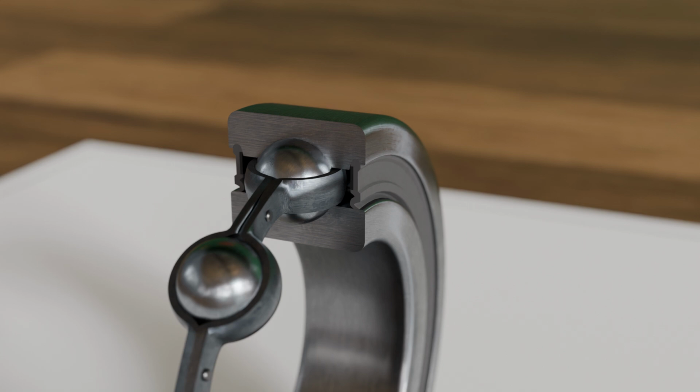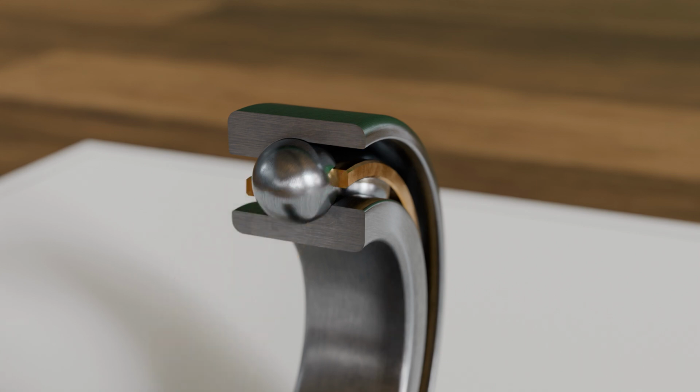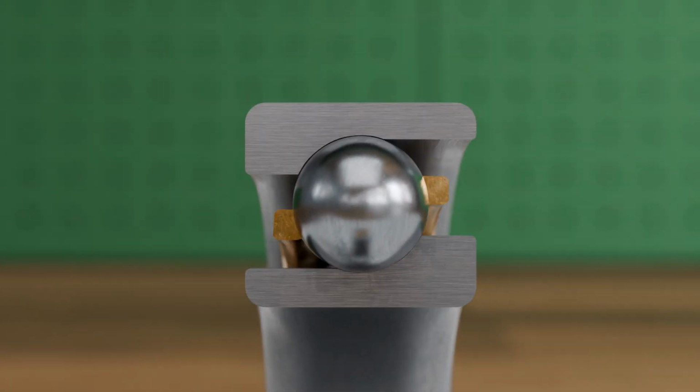When higher axial forces are expected, so-called angular contact ball bearings are used. Such single-row bearings have inclined raceways that allow them to support both radial and axial loads. In the single-row design, the installation direction of the angular contact ball bearings must be considered because the raceways are inclined in only one direction and can therefore be loaded axially to the maximum only from one side.